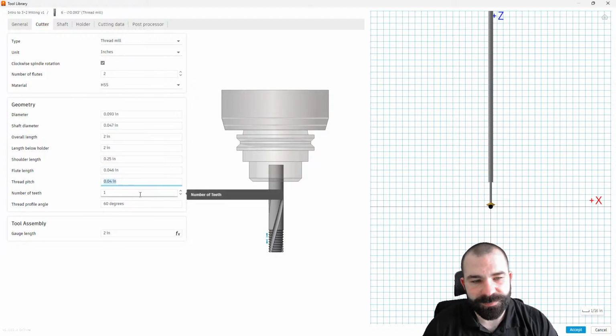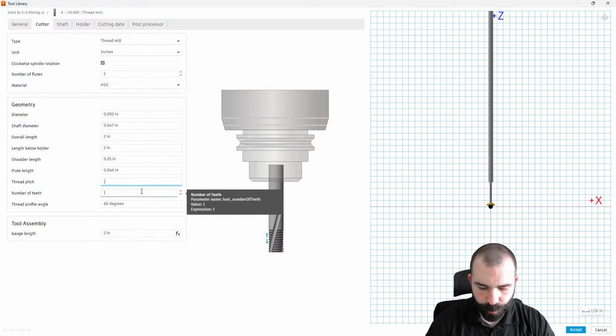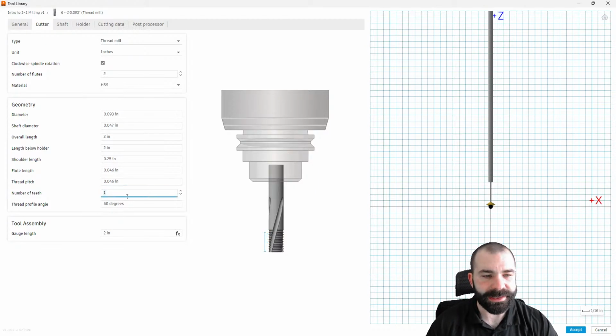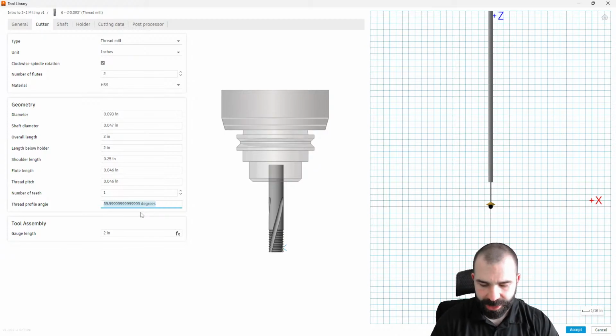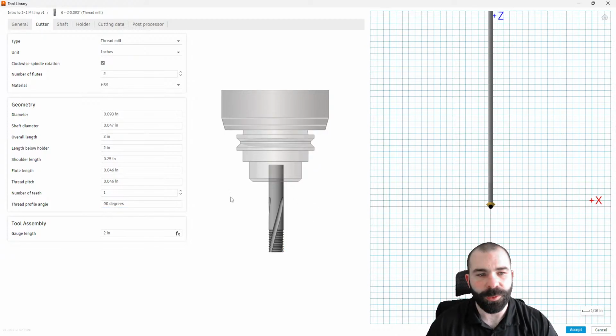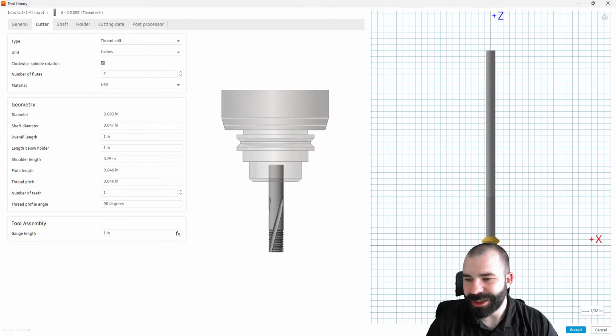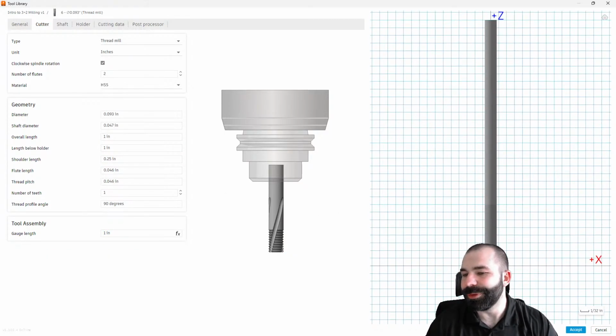As you can see, you can fill this out in any fashion that you want. Now, again, I'm going to go ahead and plug in that 0.46 a second time. And then we're going to call this out as a 90 degree or a 45 degrees. So again, probably don't need a 2-inch length on this. So let's shrink it down to 1 inch. But as you guys can see, I've now built that profile for milling, right?